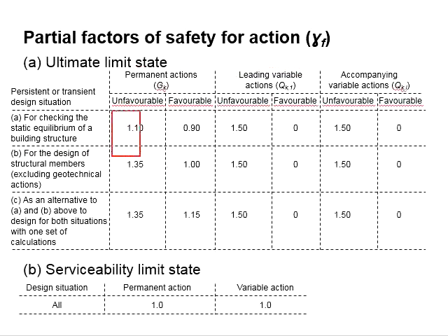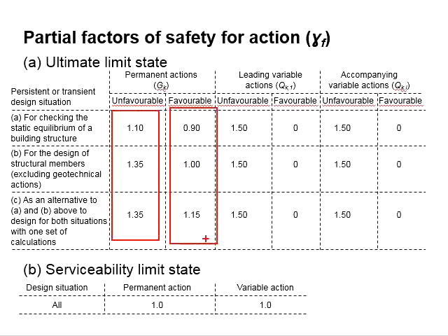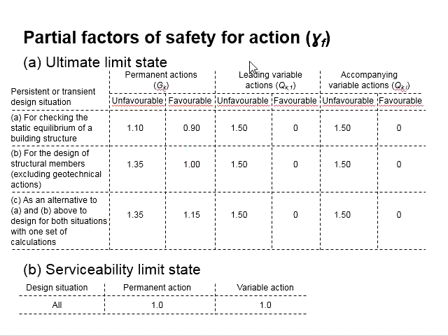The factor of safety for the favorable and unfavorable conditions differs. To simulate the most critical situations, we would increase the factors for the unfavorable actions while decreasing the factors for the favorable conditions. This is so that the structure is undergoing the worst case scenario during the analysis.